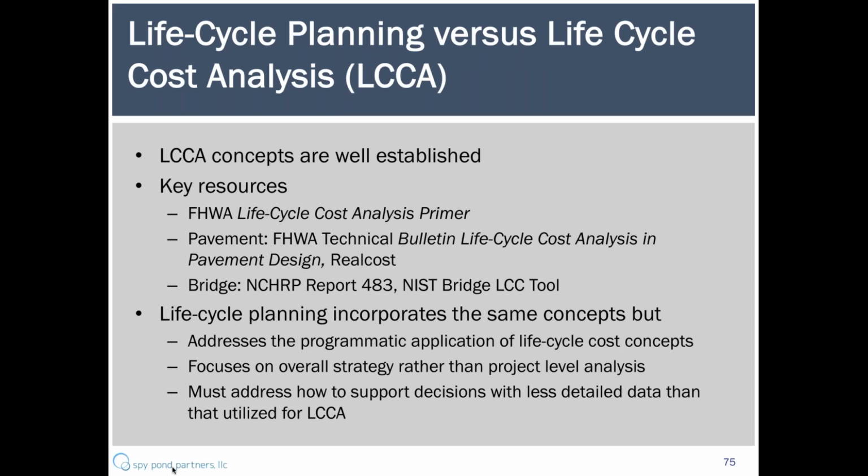Now, I think one thing that's important to clarify is just what do we mean by lifecycle planning relative to lifecycle cost analysis. And lifecycle cost analysis is a well-established thing. There's a lot of great resources out there already. FHWA has its lifecycle cost analysis primer, as well as a bulletin on how to use lifecycle cost in pavement design. That's still kind of the authoritative document for lifecycle costing for pavement. And also FHWA has the system real cost for lifecycle costing for pavement.